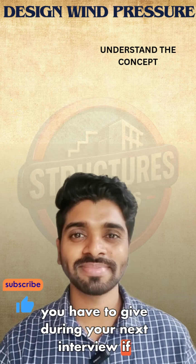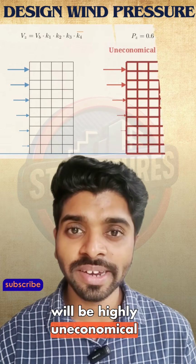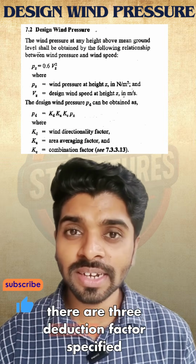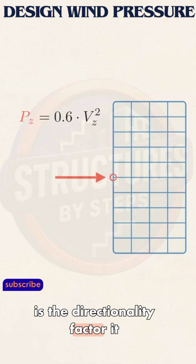If an engineer starts designing the structure based on the absolute maximum wind pressure, then the structural design will be highly uneconomical. Due to that, we have to use the reduction factors. There are three reduction factors specified in IS 875. That is KD, KA and KC. KD is the directionality factor.